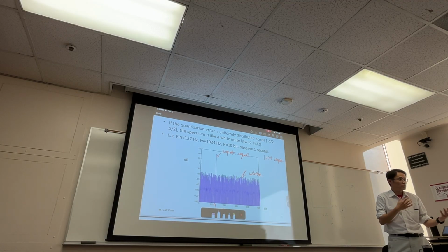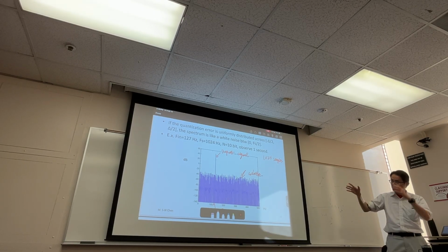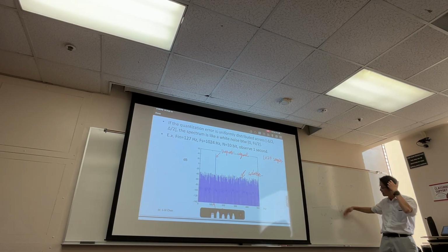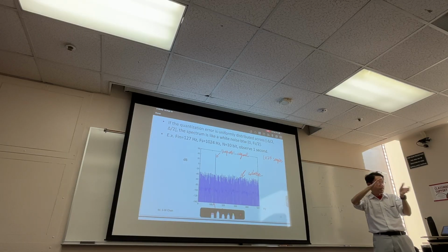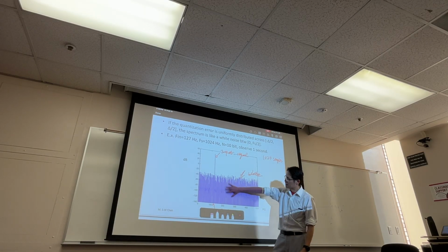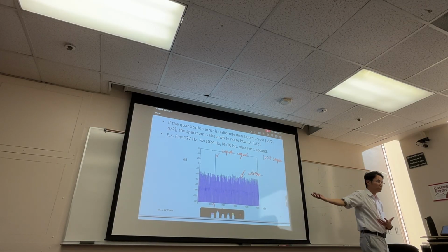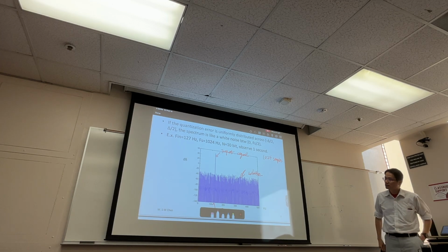So it's really signal dependent, and this goes back to what I said earlier. We need some pre-assumption. The pre-assumption here, typically when we analyze this ADC with a sine wave, is that you pretty much uniformly distribute those V errors. That's why you get this more or less white noise from your V error, your quantization errors.